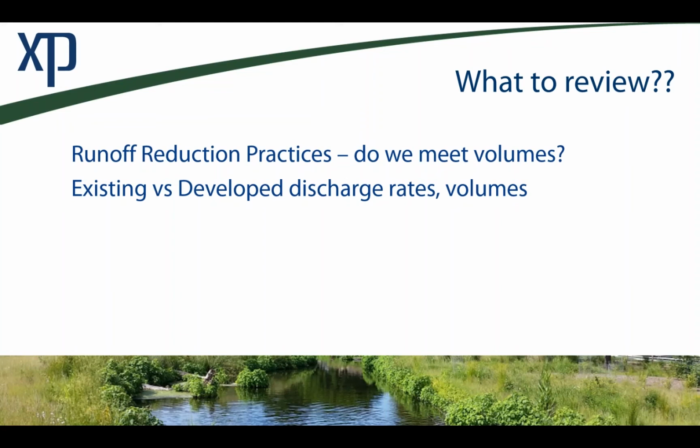Now, this might vary based on where you're at. The trend is becoming a bit more strict as far as design goes, but certainly for years and years, the basic stormwater focus was on reducing the discharge rates off a developed site. We're beginning to see a lot of groups, a lot of municipalities, a lot of university studies showing how important it is to control the volumes off of our site. So for many groups now, not only do you have to control the peak rate off your developed site compared to the existing conditions, but also now you can't discharge any extra volume.